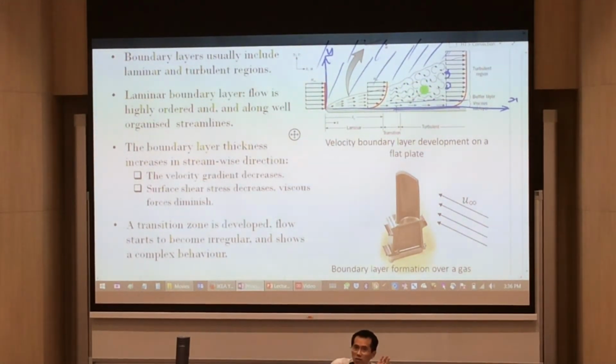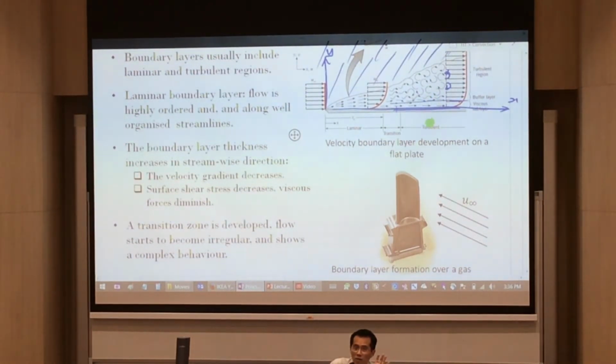it's turbulent. Why? That's because if I want to encourage heat to get transferred away from the plate, my laminar flow is not my best flow to remove heat away. My turbulent flow is the one that's going to remove heat away. Why so? That's because I don't have to let the laminar flow convect the heat away. But turbulent flow just kind of digs away whatever heat is on the surface.